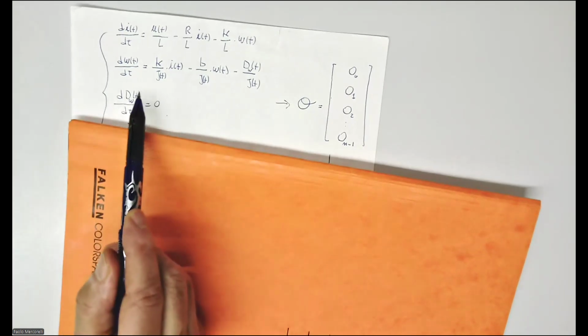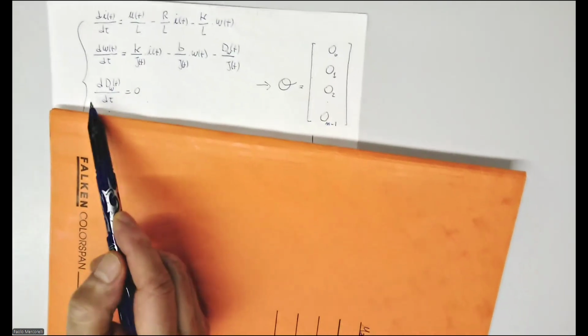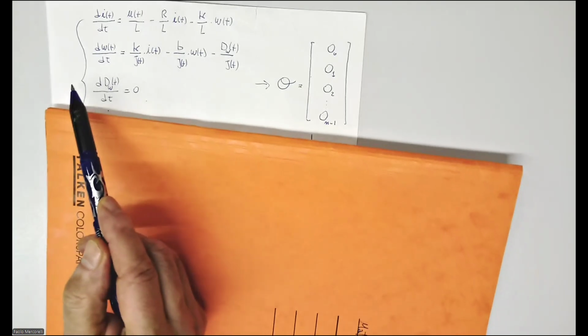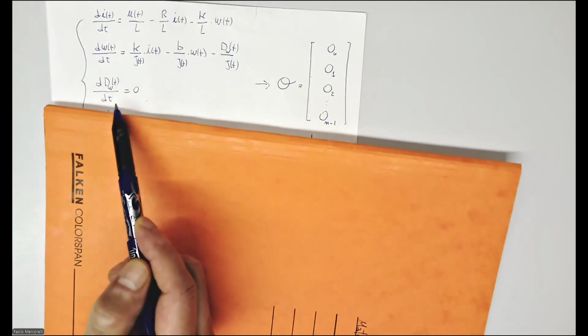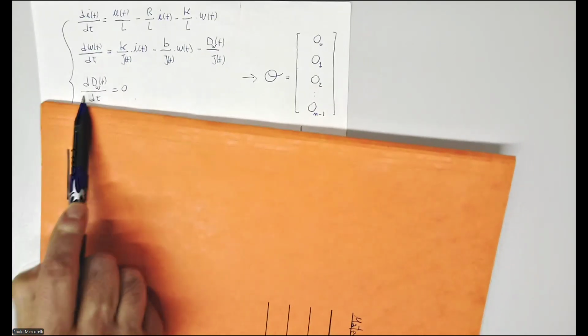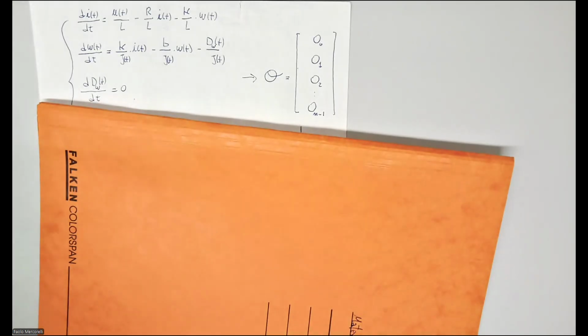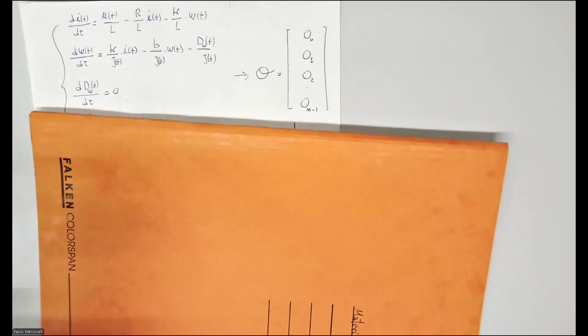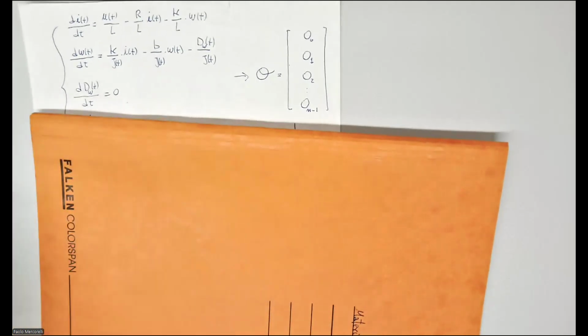I mean, this expression here is, in a deterministic sense, extremely strong. Do you remember? I repeat it many times, because this means that the disturbance is deterministically constant. But inside the Kalman filter, I can realize a stochastization using the Q component corresponding to this variable. And in this sense, it becomes possible to estimate it.